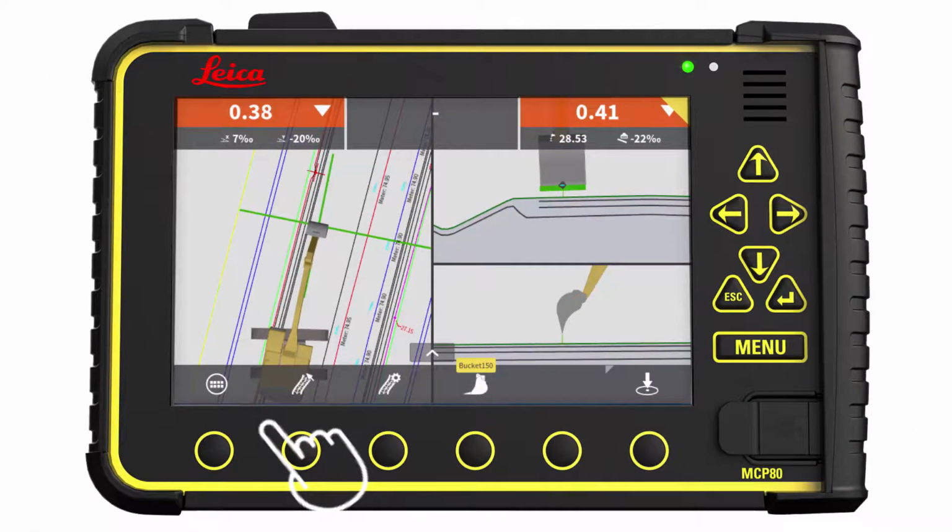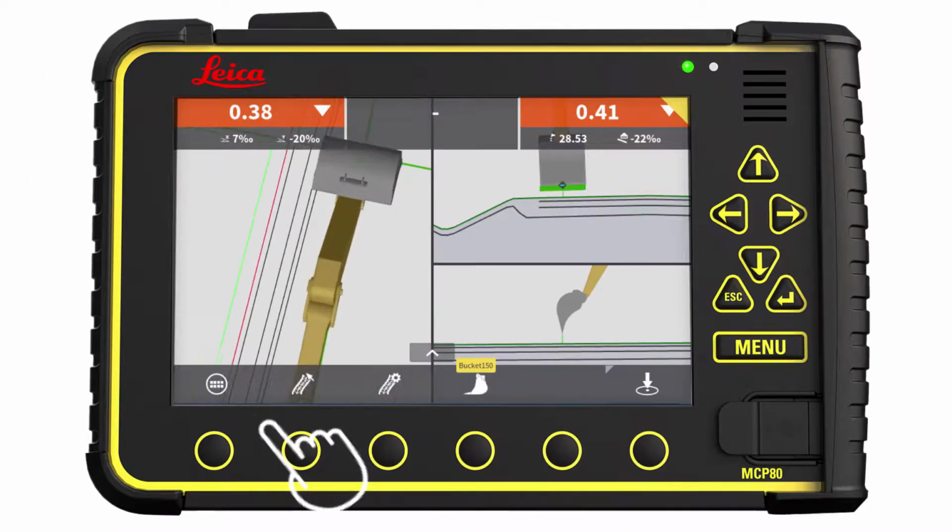One of the benefits of keeping everything in one file is that we can select a line as our site reference and we can make a height offset on our surface. Let us see how that works. In this example, I would like to make a small trench for some cables, 70 centimeters under my finished grade.